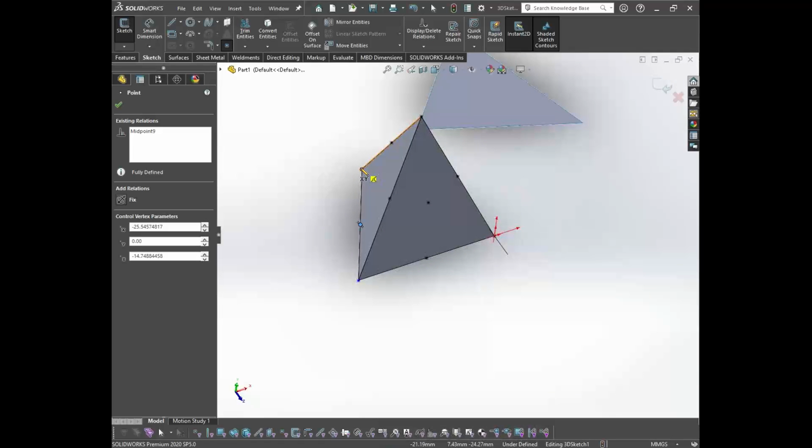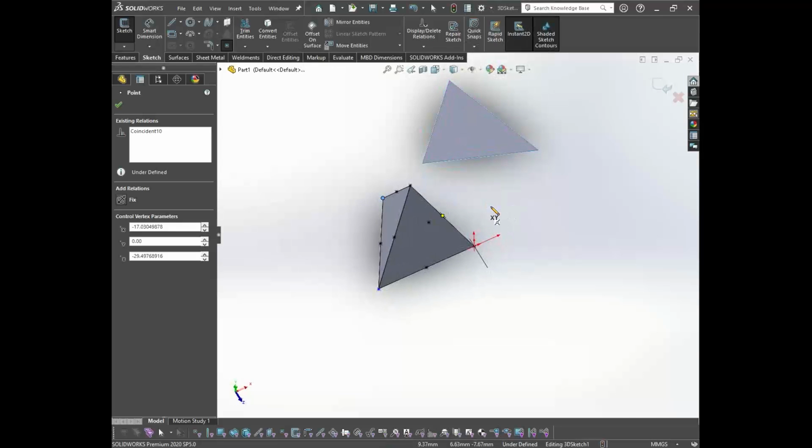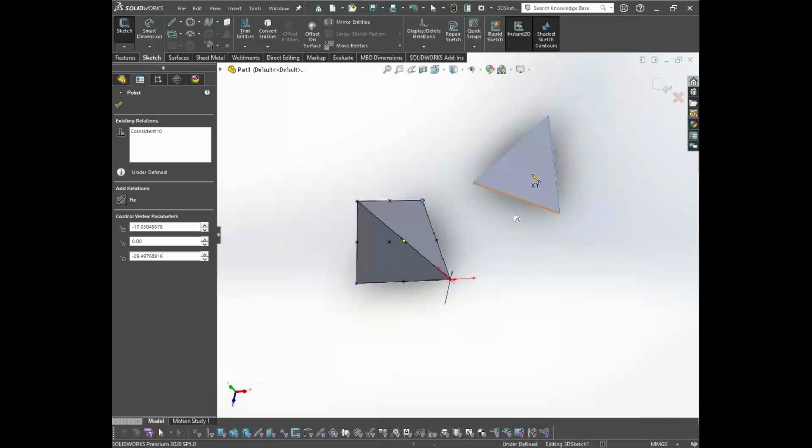Earlier, only the 4 node locations at the vertices were deforming and capturing the data for the calculation purpose. Now it gets more mid nodes for calculation purpose, so it will try to capture more deformations related to this particular element. So more data is captured in this process. This is how you can define the high quality or parabolic mesh element. This comes with the tetrahedral.